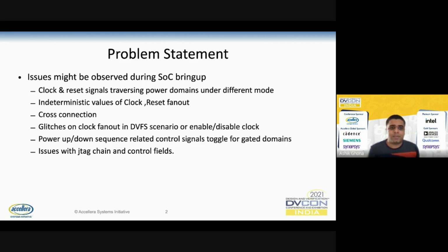We'll discuss the issues we are going to address. First is clock and reset signals traversing through power domains under different modes. In an SoC, we have functional mode, test mode, and debug mode, and clock and reset signals behave differently in each mode. Next is indeterministic value for clock reset fan outs. We might be seeing unknown values on clock and reset fan outs, and in some simulations we might be seeing X.